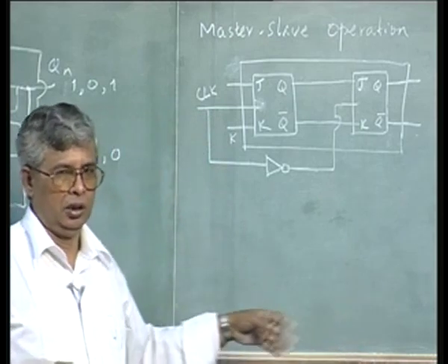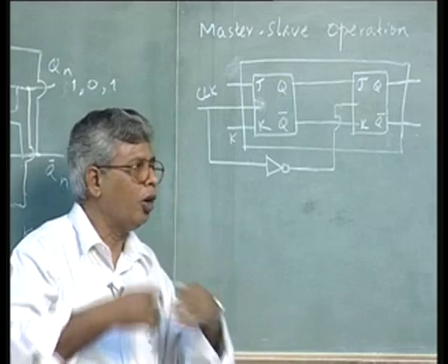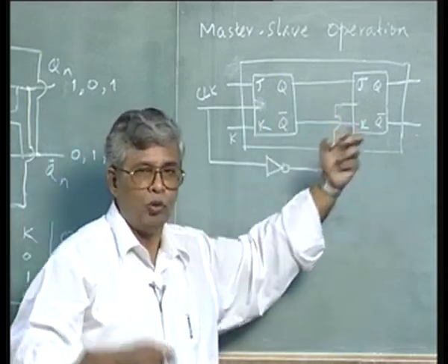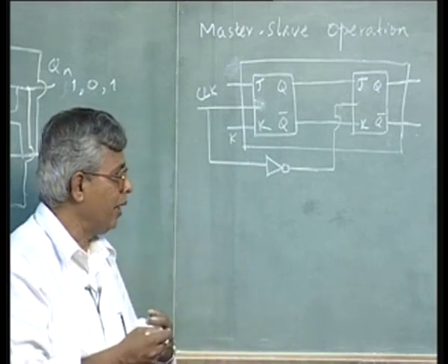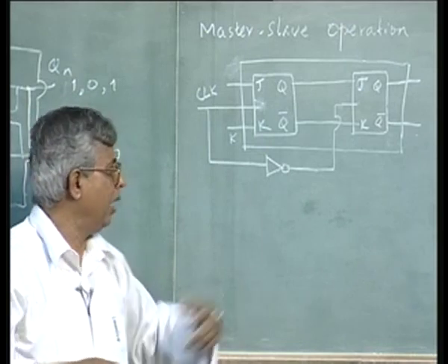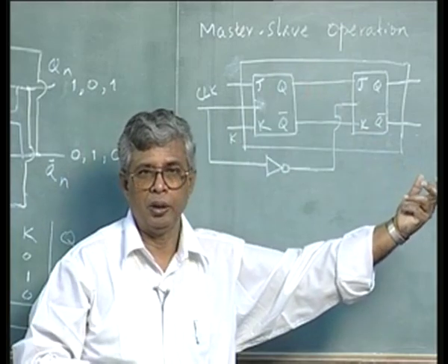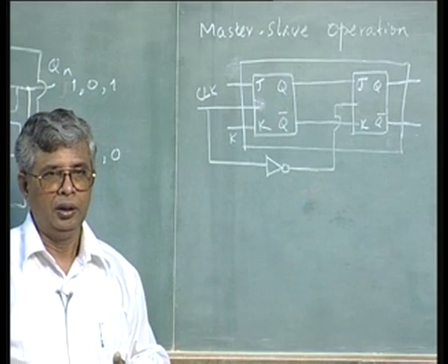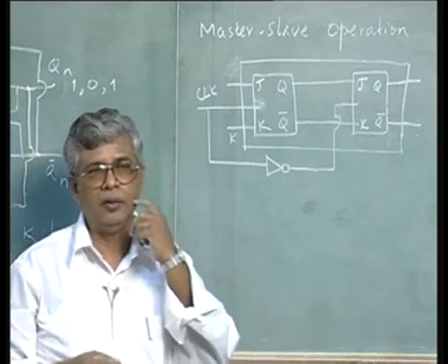Whatever it is, I do not want to question your need. Supposing you want to operate at a clock rate which is faster than the propagation delays which two flip flops can allow, why should I be restricted in the speed of operation by having to pass through two flip flop hardware? Why should I unnecessarily increase the propagation delay of the path if it is not required, plus the fact that there is extra hardware required. That makes you think whether it is the best solution.